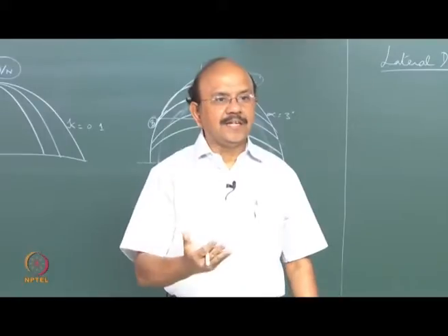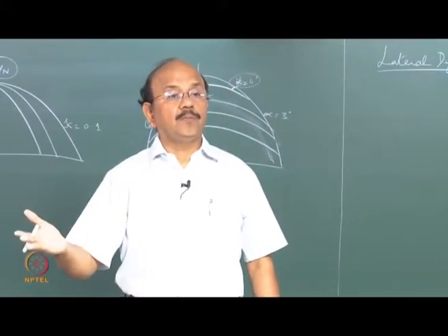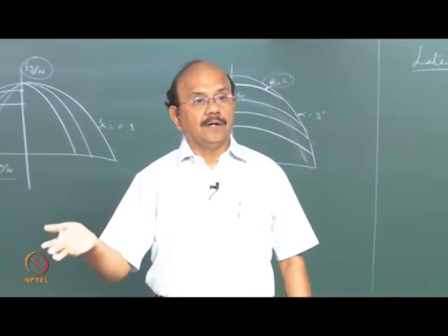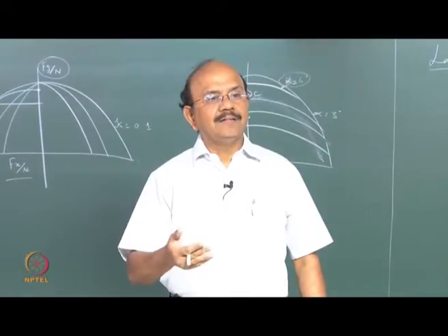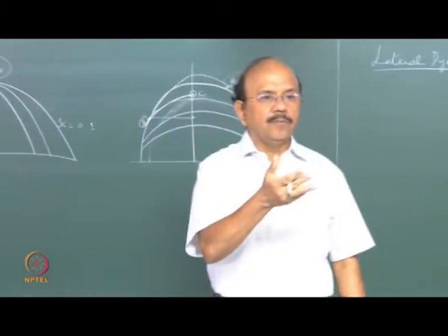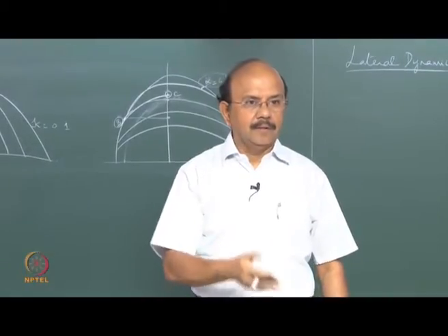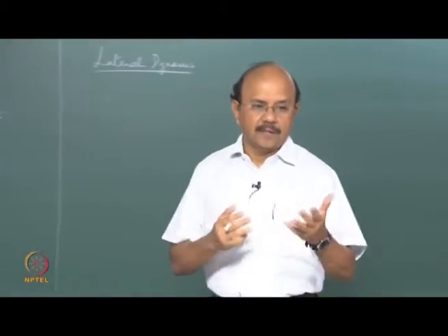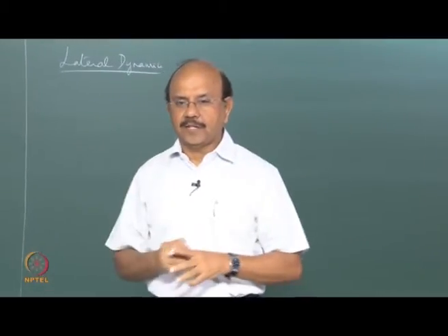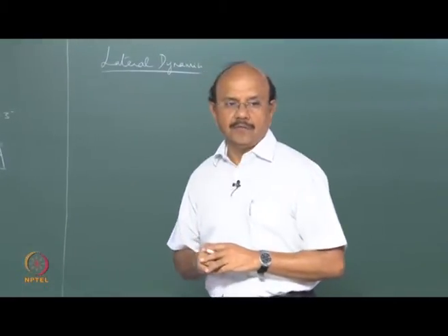So when the forces suddenly increase, and it's more than what needs to be compensated by the centripetal force, then there is no equilibrium, there is loss of equilibrium. So in other words, you overturn. Clear? Okay, we'll come back to this maybe towards the end of this lateral dynamics, so that you understand it better. But I'm only telling you that there are practical applications of what we're going to study.